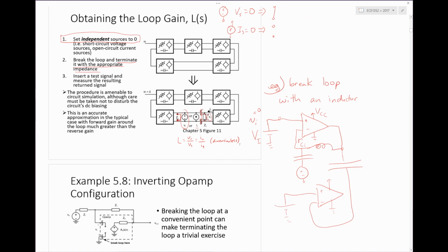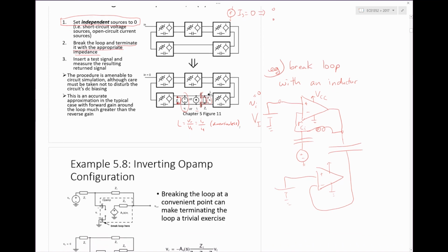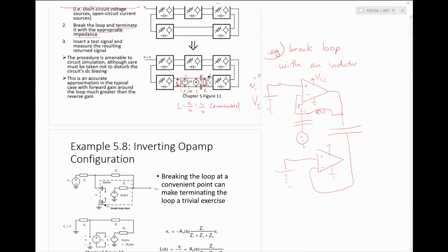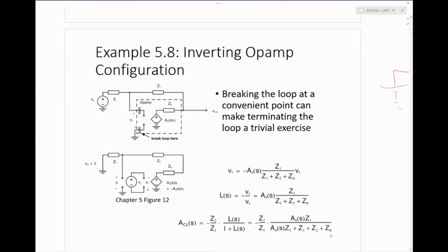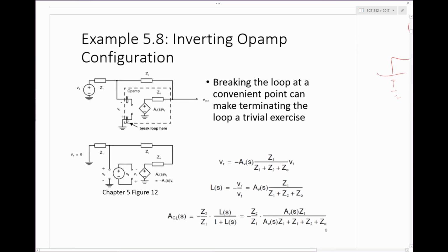Okay. And then since these are real transistors you have connected here, they'll vary with temperature and process in the exact same way as the real load does. Okay, so those are some nitty-gritty tricks that you may find useful.